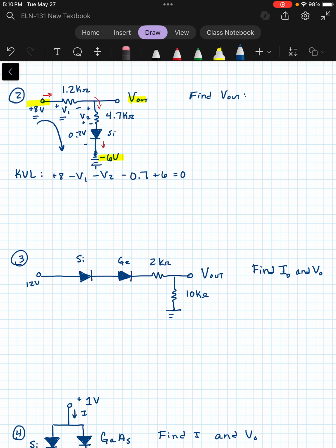That may be kind of hard to see, but whenever you see something in the circuit, for instance, you have 10 volts here, a positive 10, you can just replace that with a 10 volt source to ground with the positive terminal at the measuring point.